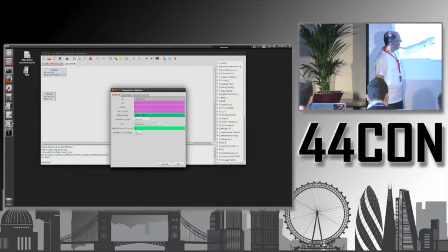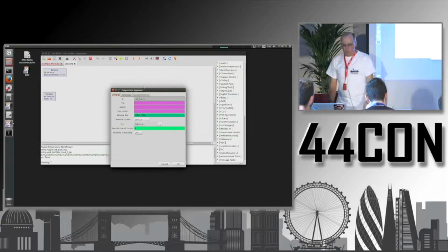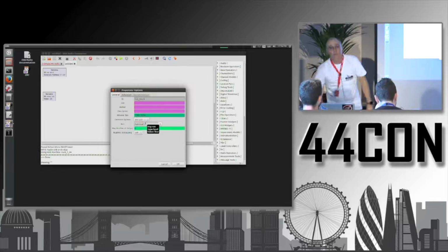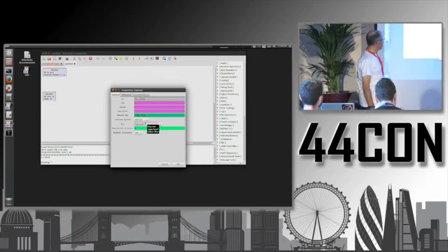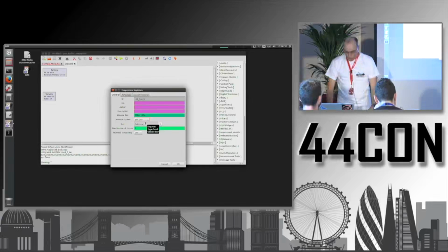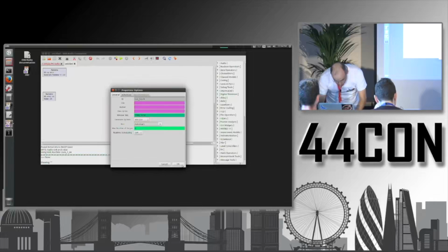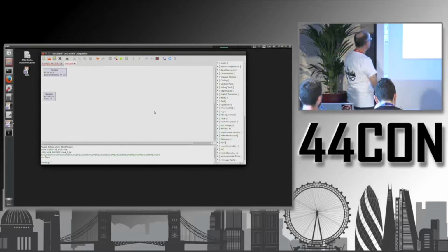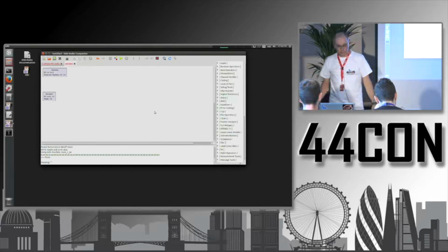What I'm going to change here, and you do that best too, in generate options, we are going to use another GUI, the WX GUI. Okay? And then you can accept this. So that is our first change. Now we can leave this block alone, this is fine. This block here defines a variable, the sample rate.